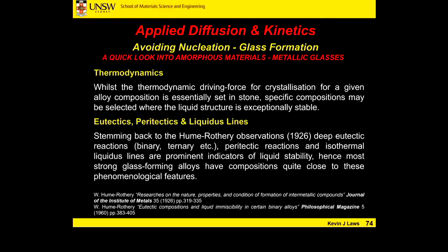What do we notice about this point here? A eutectic reaction point. Its melting point is lower than both of the pure metals to start with.